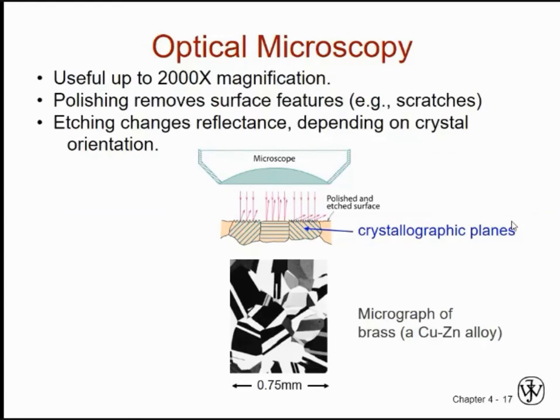We use microscopy to analyze materials: grains, specific grain size, grain boundaries, and phases in grains. For example, we may have some heat treatment on a material, and we check with microscopes if we have done the heat treatment properly, or we can measure grain sizes to define material properties, because grain size defines material properties such as hardness, ductility, strength, and so on.